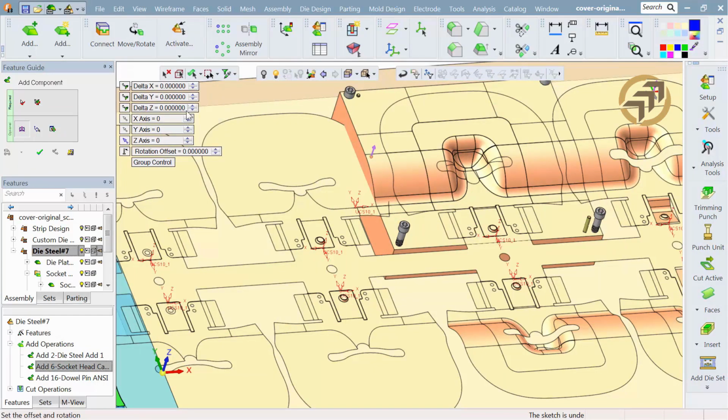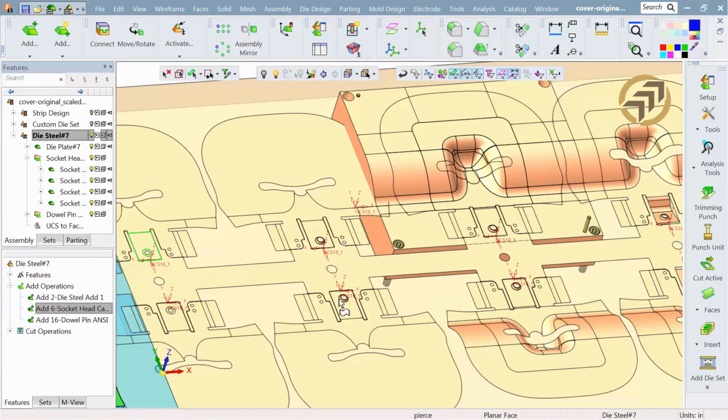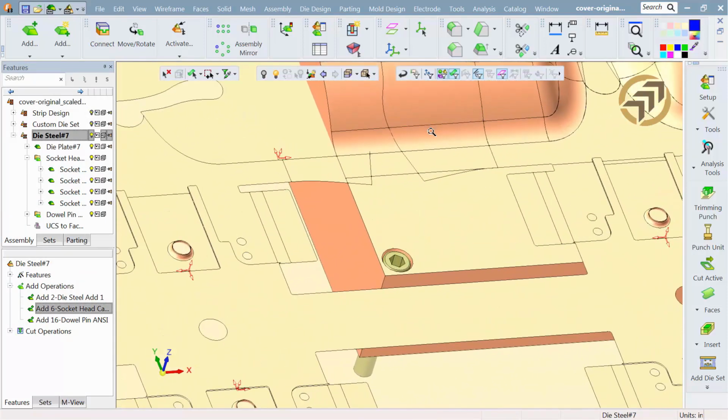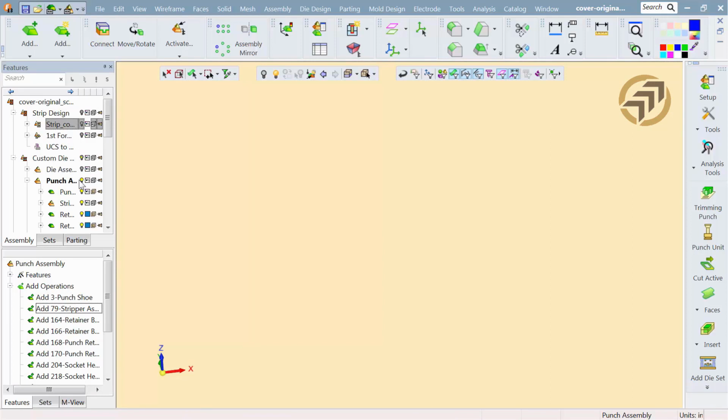Let's now drop that in. We'll recess it a little deeper. You can recess things based upon rules. Here I'm just dropping it in so that I know it's deep enough within the steel. Now as we calculate it, you'll see it also updates the hole that sits in it. So there you see the counterbore on the opposite side has been drilled and tapped.